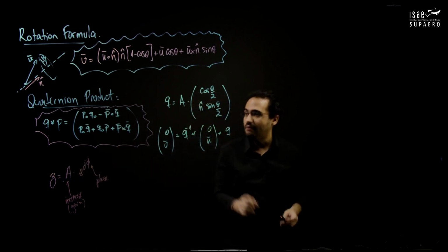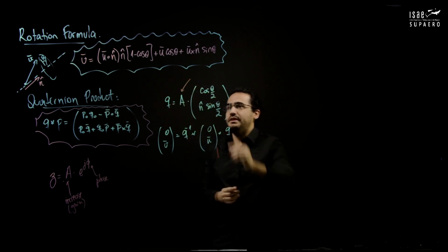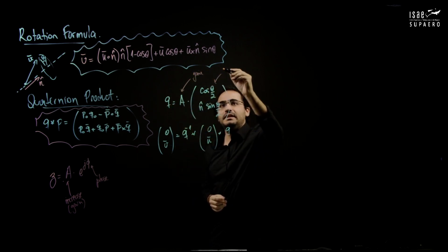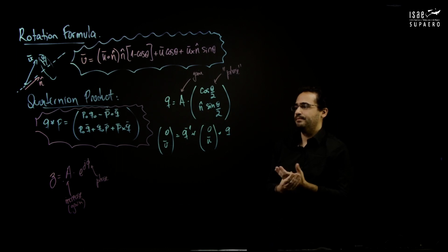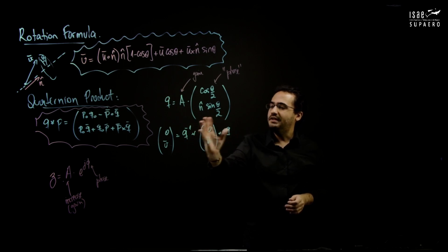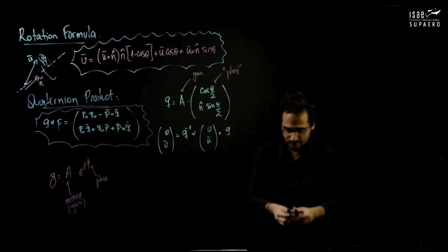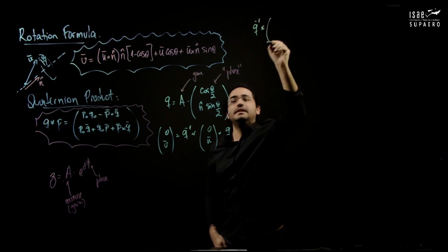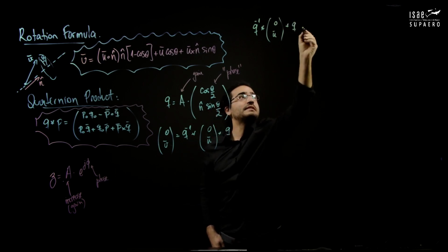And in a very similar way, I want you to think now that any quaternion can be written as this, which will be a gain. So the norm of the quaternion is the gain, and this would be, in some sense, a 3D phase. Okay? So when you multiply quaternions, this multiplication will add a phase and will add a gain. And the way to rotate quaternions is given by that. Now, we will go through this just to show you that that is indeed the case, and also to practice a little bit quaternion multiplication and other concepts that we'll see very shortly.